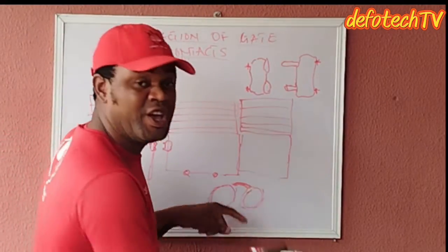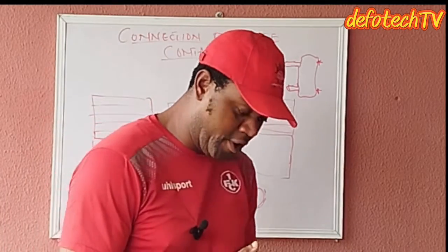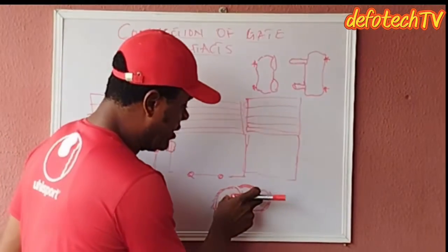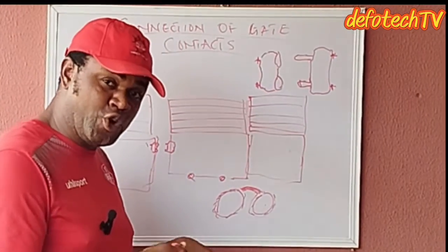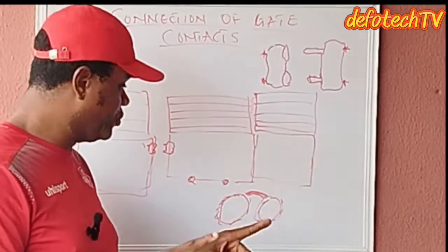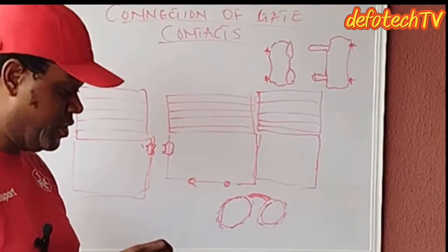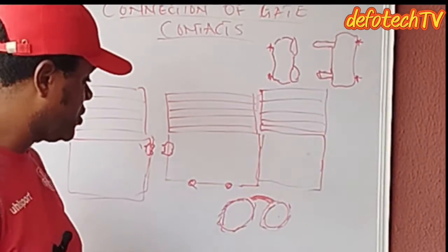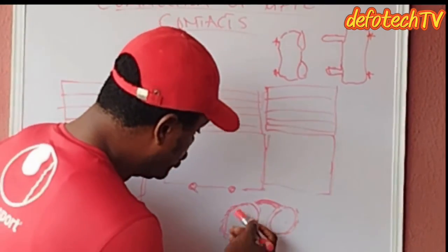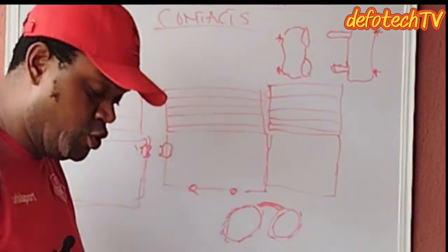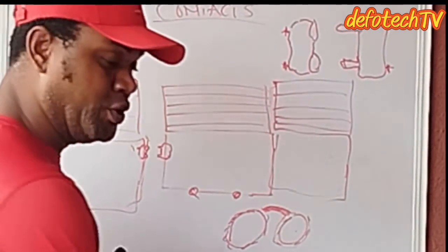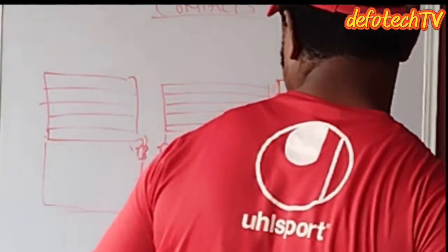Maybe it's pushed out. If you want to test this, if you get a gate contact, all you need to do is push the spring, push this contact in, and use your avometer with a continuity test to read it. You will notice the line is open, no longer closed. But by the time you remove the spring, allow the spring to spring out and push the metallic conductor there to touch this other part here, use your avometer on it, you notice the contact comes back to a closed position. So that's just the way the gate contact is designed.